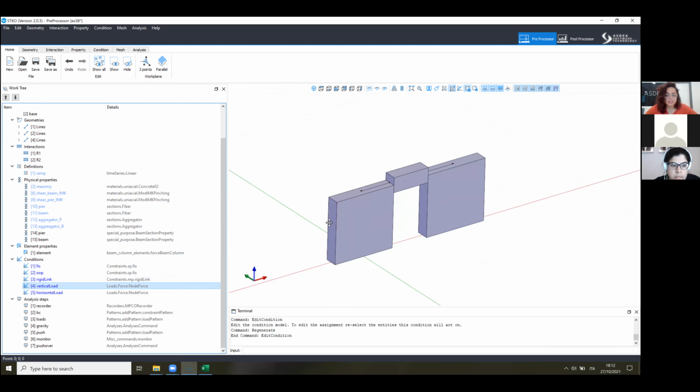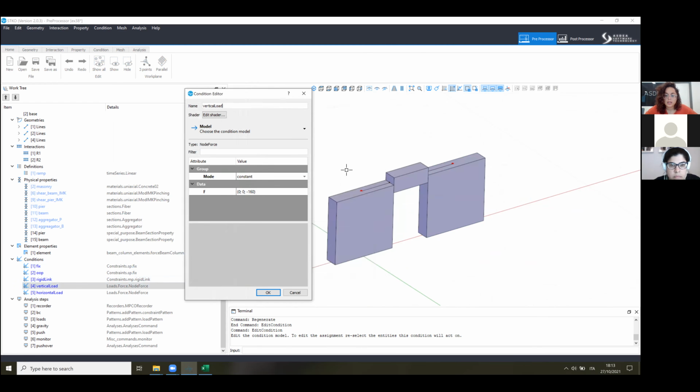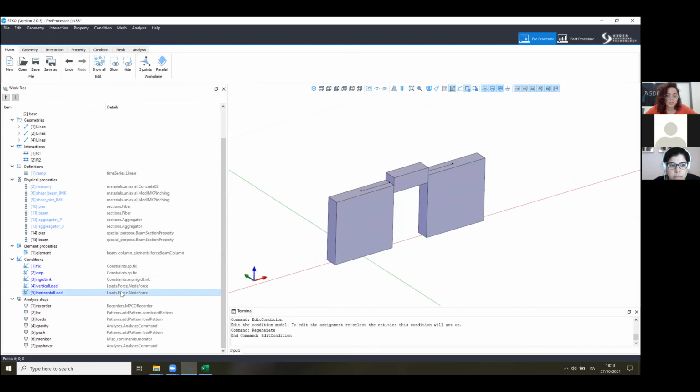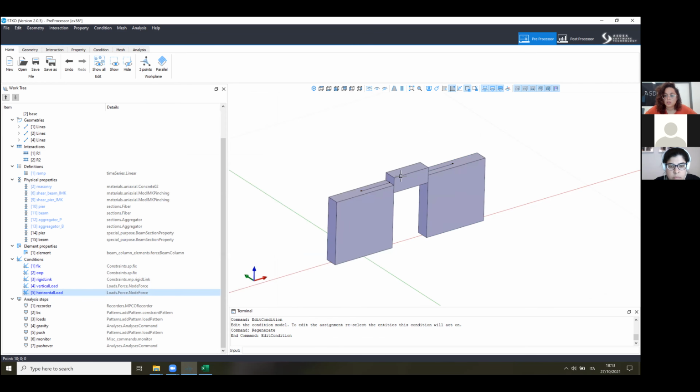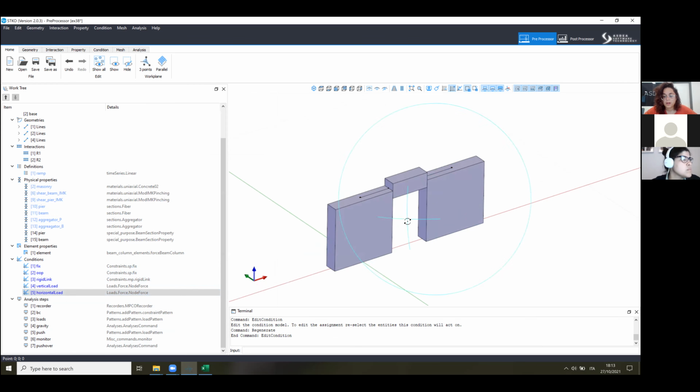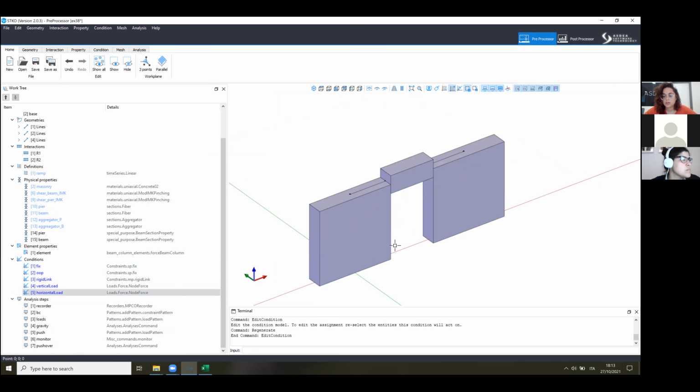We just applied a vertical load to the two elements on the sides and a horizontal force to operate a pushover with displacement control, moving the structure 35 centimeters. Like this, you have no account for shear behavior. These kinds of elements only mimic the axial and the bending behavior of a masonry wall, but that's not at all realistic.